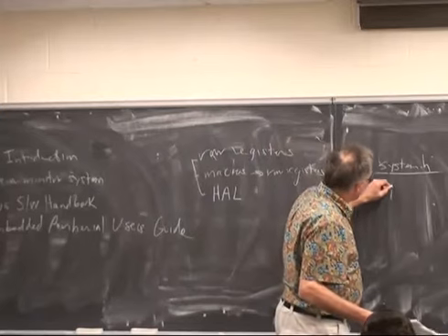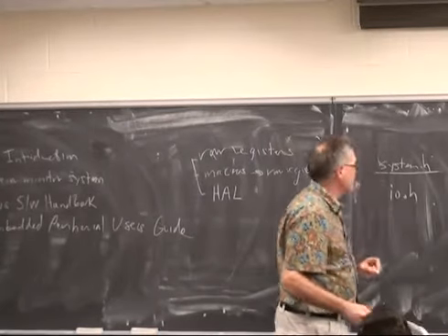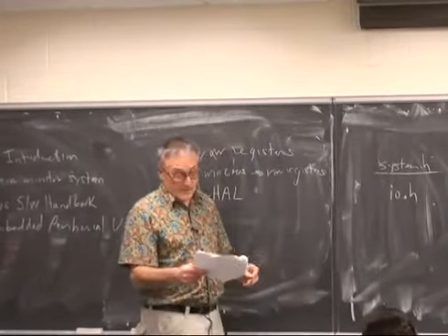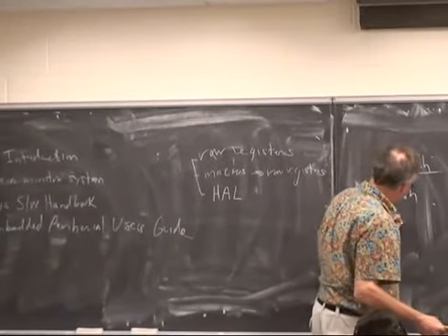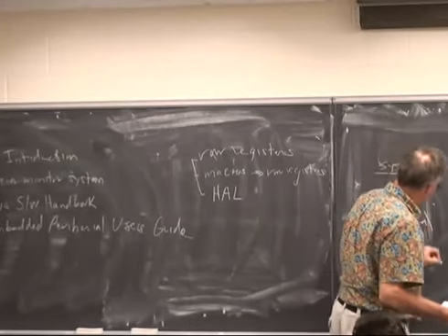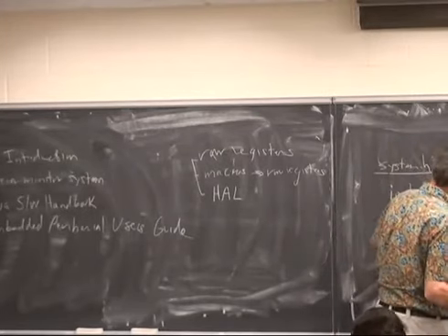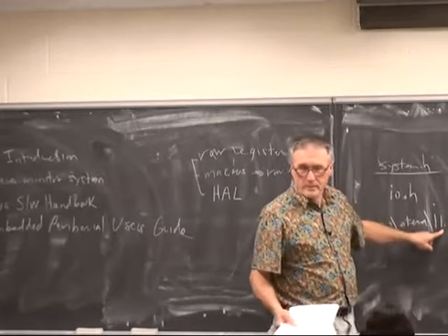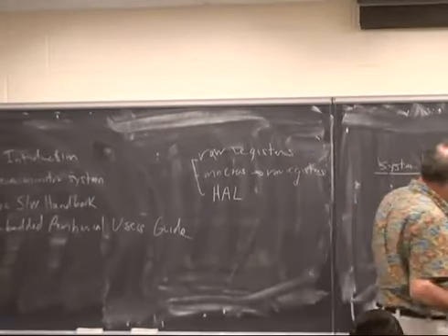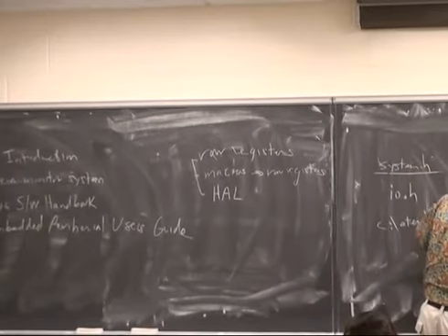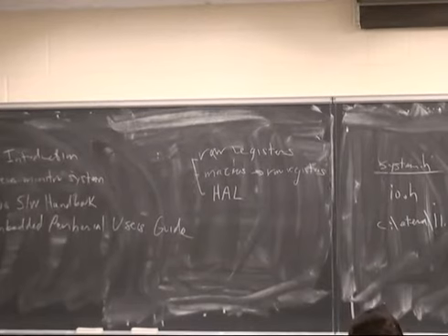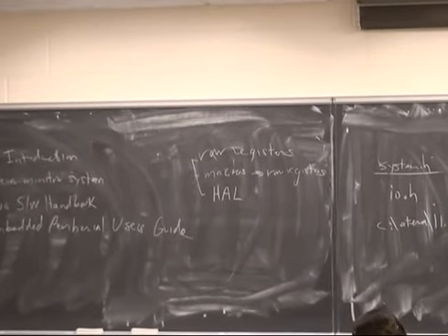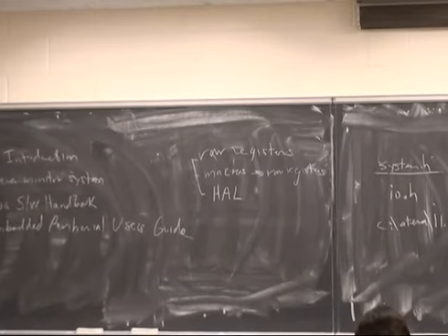You're also going to want to look at io.h. That is in an obscure location, which took me a while to find. C, Altera, 11.0, or whatever the version number is that we're using in the lab. I think it's 11.0. Altera, SOPC underscore builder underscore IP.